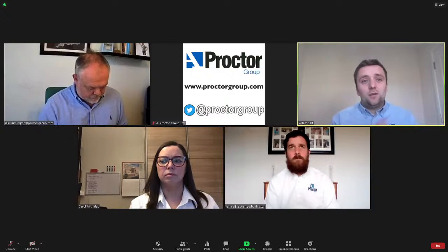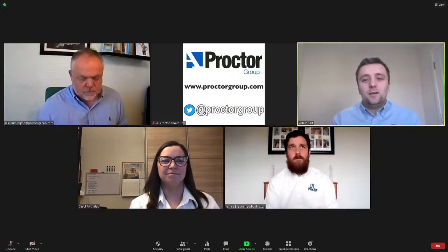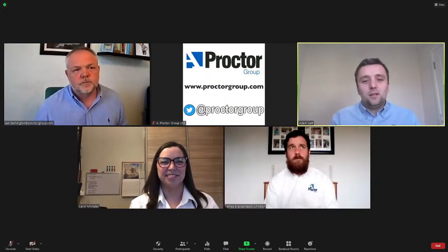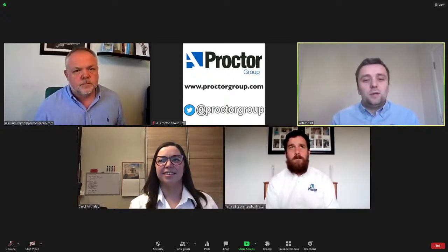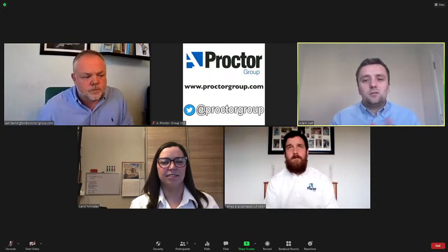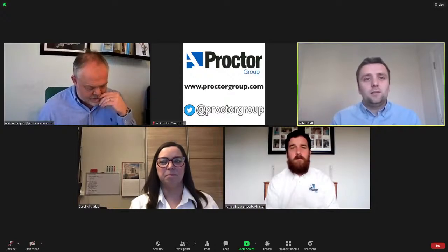If you're like me, however, who's at home all day, sat in my home office, and don't leave the house for long periods of time, then you'll be more suited to external insulation, because although it takes longer to warm your property up, once you turn that heating off, the heat is retained for a lot longer, because you have a higher thermal mass internally in that method. But yeah, a number of things to consider. Hopefully there's a couple of ideas for you there.